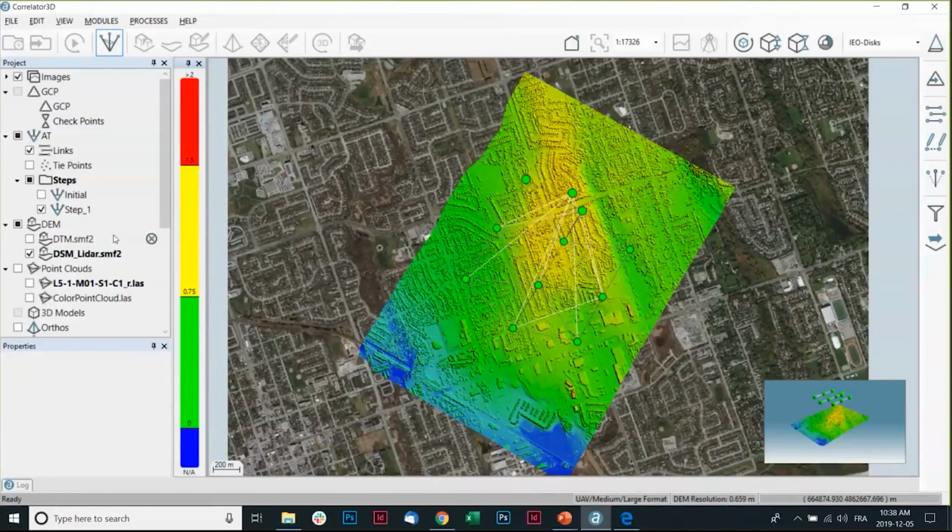On the other hand, if you're doing an ortho rectification on your terrain data, it's only going to be the terrain deformation that will be corrected. So you'll still have a leaning effect for some buildings or trees or cars, depending on the acquisition parameters. The leaning effect could be much less if you're flying at a really high altitude, but could be really important if you're flying at a low altitude with a non-metric camera on a UAV. The leaning effect could be a challenge here, so you really need to ask yourself what is best suited for your needs.